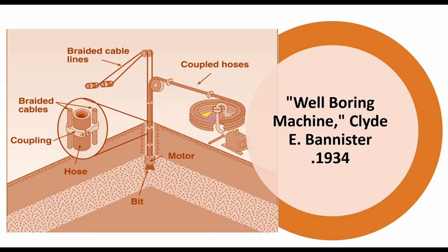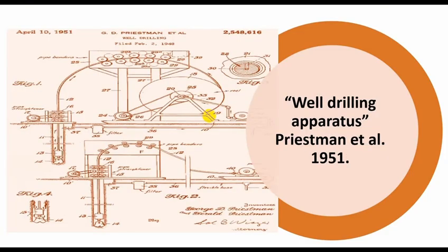So later, Priestman et al. invented the idea, which was previously used in World War II, of inserting steel pipes into the well while drilling, not a live well. So no pressure control equipment was used. While drilling, the steel pipe was wound around the drum, and was given the radius of curvature by benders like the gooseneck currently, and then back to straight pipe through a pipe straightener.